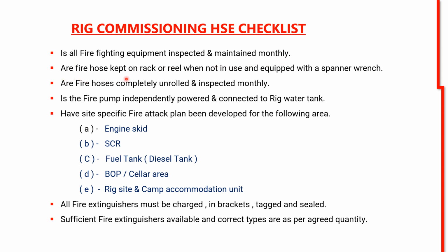Are fire hoses kept on rack or reel when not in use and equipped with a spanner wrench? Are fire hoses completely unrolled and inspected monthly? Is the fire pump independently powered and connected to the rig water tank? Have all specific fire attack plans been developed for the following areas?